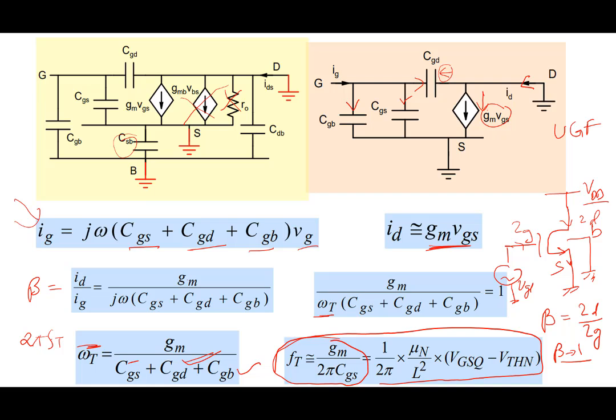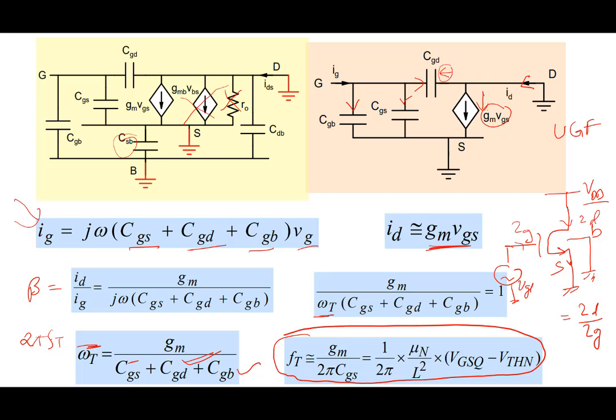Below FT, it may be of some use, right? So you could use it. So it's the highest frequency at which the MOSFET could be considered a useful device. This is an important expression which tells you the upper limit on speed of a MOSFET, the unity gain frequency of the MOSFET here. Just like for bipolar we were studying, similarly now these are all based on long channel theory. Assuming the MOSFET is fairly long, no short channel effects and all that are taken care of. So it's based on long channel theory.